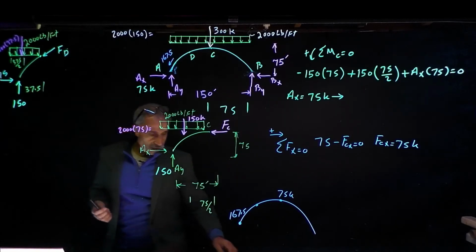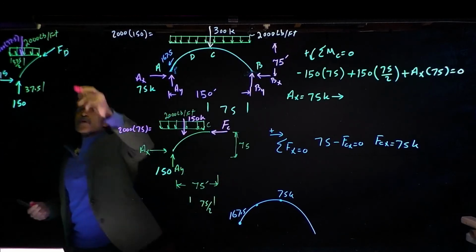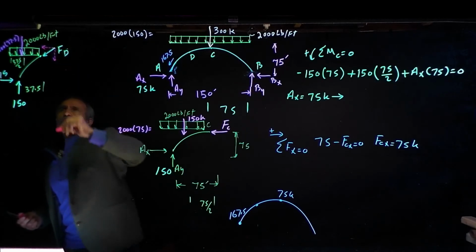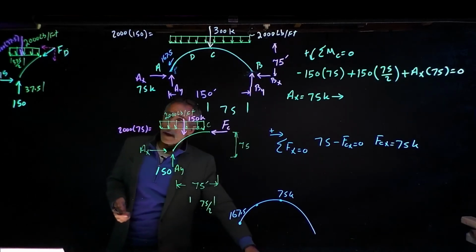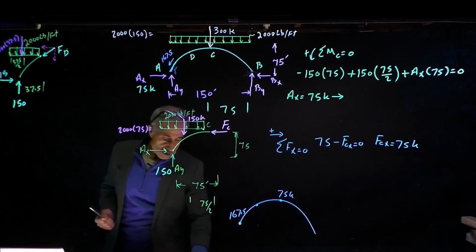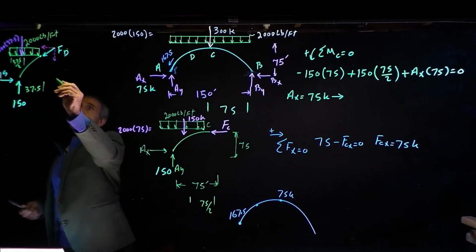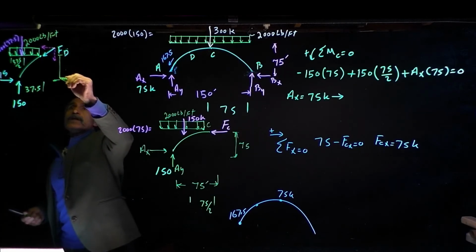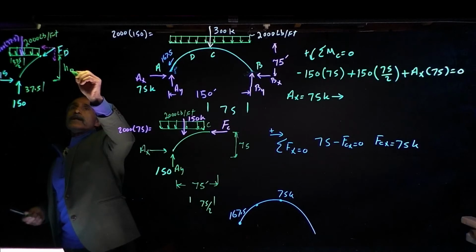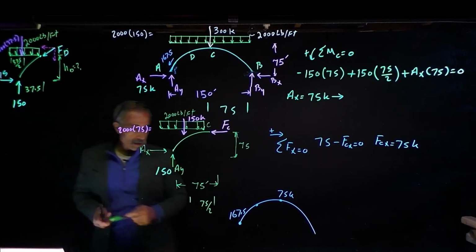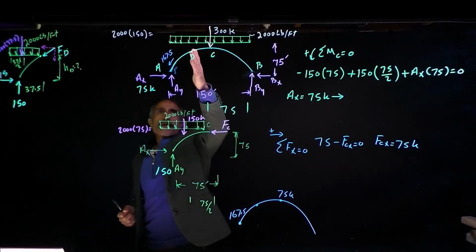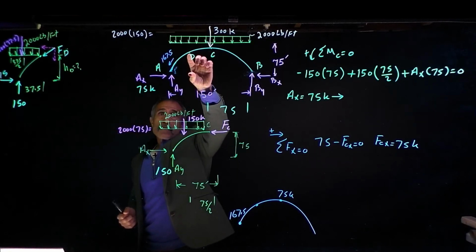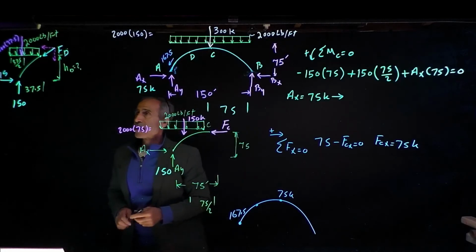But remember, something you got to keep in mind is that this force has two components now. It has a y component and an x component. And I don't know this height either. This height right here, up to here, that's h d, we don't know. So what we did here, we cut the arch right at point D, and we'd like to know what the force is here, but I don't even know this height. We can figure it out, not a big deal.